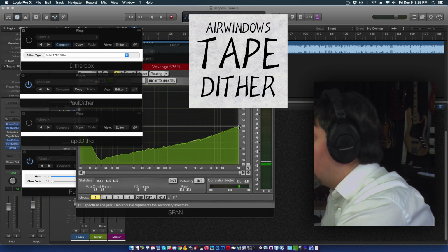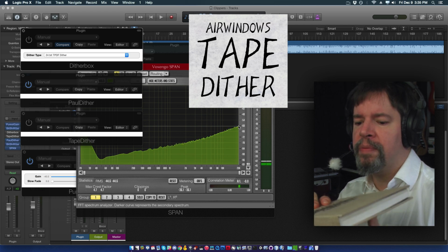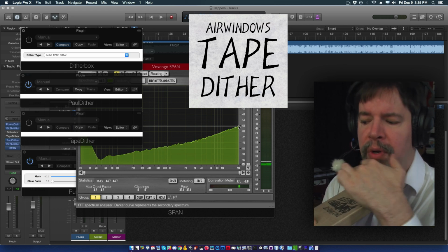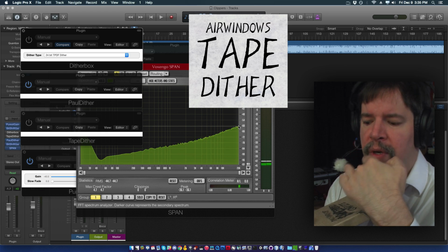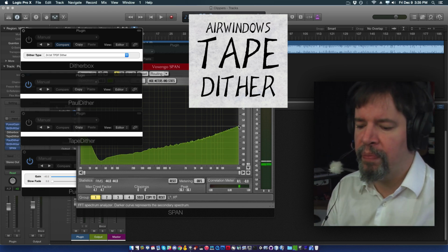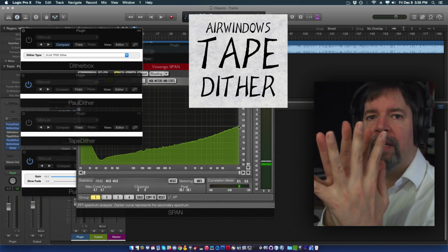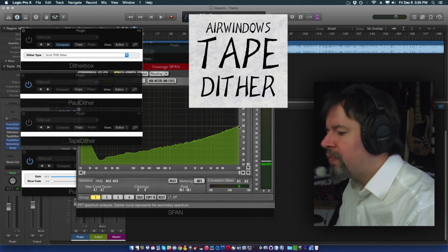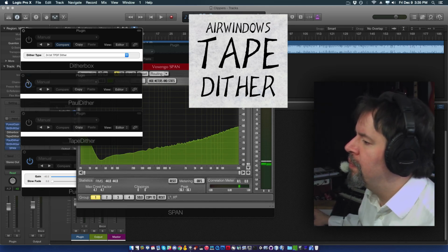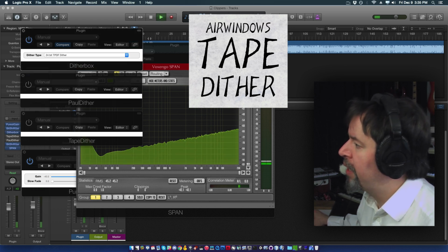Cancellation effects are like what you get when you have a surface near your voice and the sound of your voice goes directly to the microphone, but also bouncing off of the surface and onto the microphone. You get two copies of the audio waveform and they combine destructively. So what we get here is with a single sample, come on, wiki.